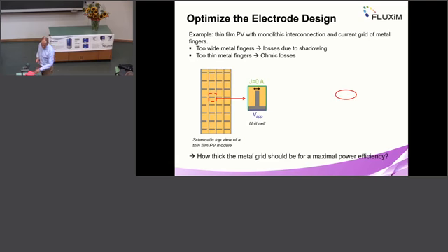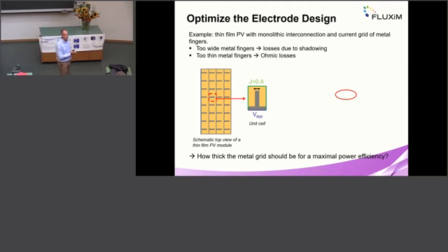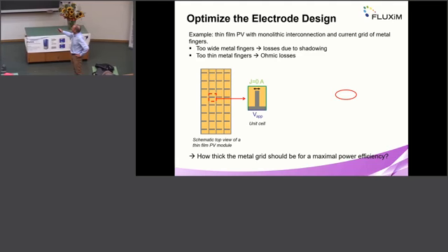So let me look at a quite popular monolithic solar cell design. This is a top view of a solar cell mini module where we have 4 cells connected in series from left to right. They are elongated solar cells, and there's always the top electrode that goes back to the bottom electrode in this interconnection.